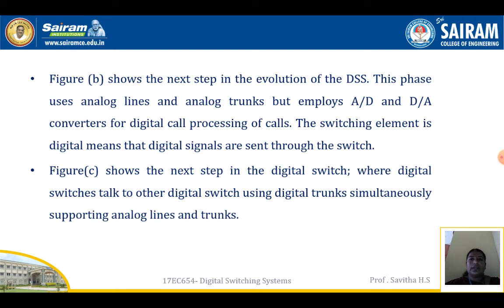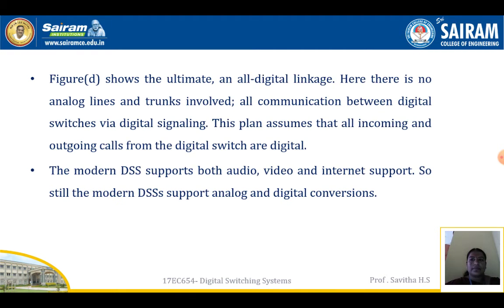Figure B shows the next step in the evolution of the DSS. This phase uses analog lines and analog trunks but employs analog to digital and digital to analog converters for digital call processing of calls. The switching element in the digital means that digital signals are sent through the switch. Figure C shows the next step in the digital switch, where digital switch talks to other digital switch using digital trunks simultaneously supporting analog lines and trunks.